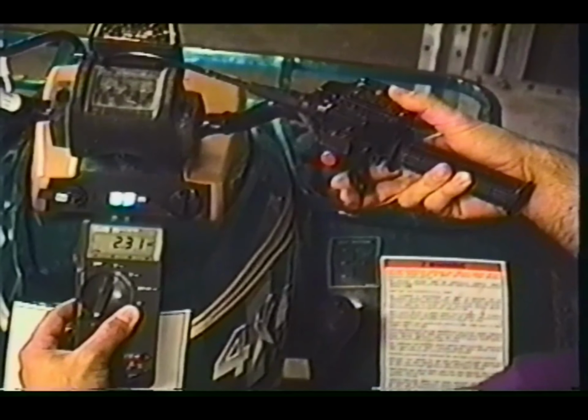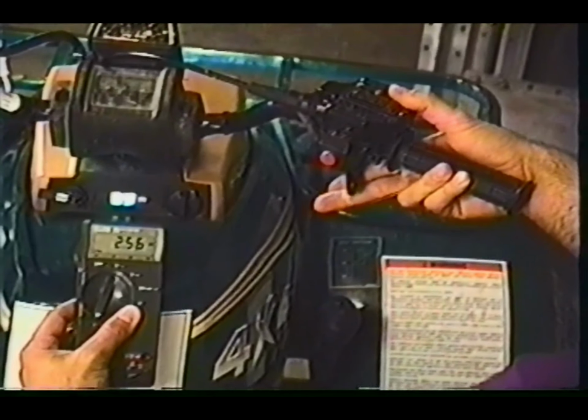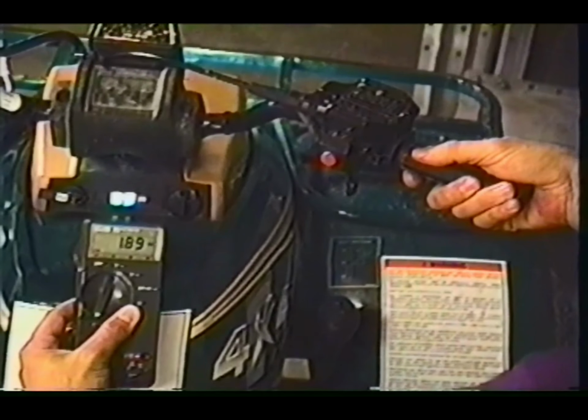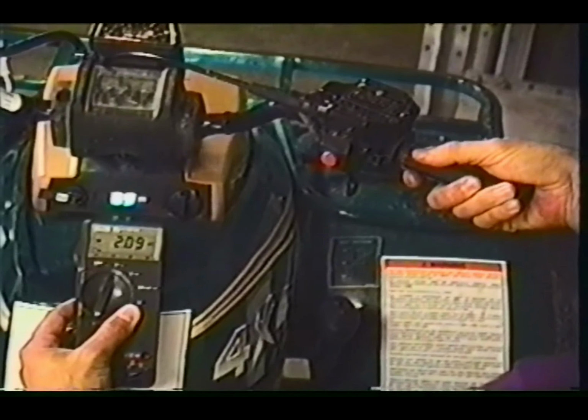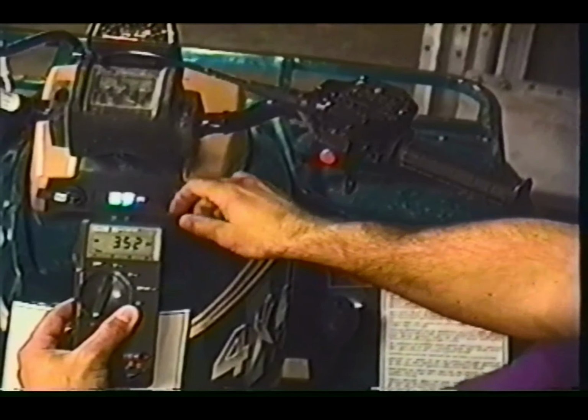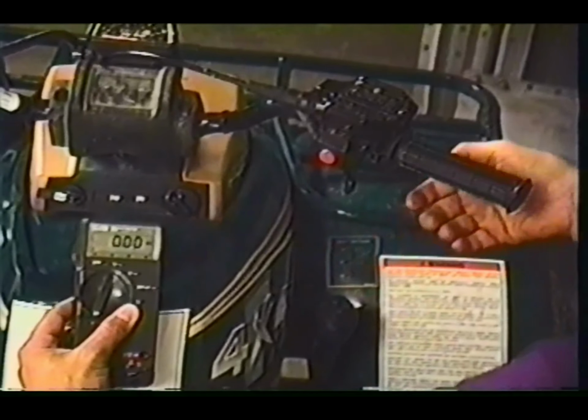It will show a negative number if there is a current being drawn from the battery. Increase engine RPM to see if and when the battery starts to charge. This point is called the break-even point. If the customer continuously drives below this RPM, the battery will never charge.